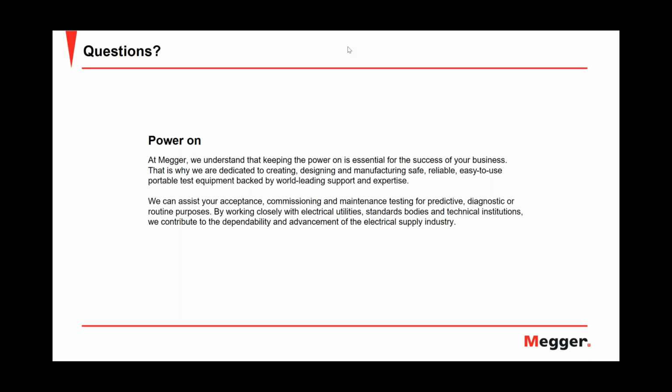Typically on XLPE cables, like Javier explained, you expect the breakdown to be well below 12 kV. So just set it to a reasonable number. Don't overvoltage it to crazy values, just let it ramp up and wait for the breakdown. So you're not carrying out a DC proof test.